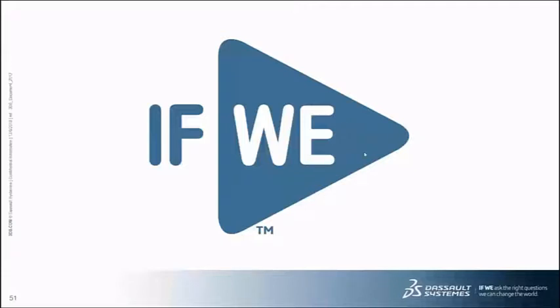How about dynamic implicit method to resolve convergence issues? Yes, I've started to use that more and more. And frankly, I prefer implicit dynamics with the application for quasi-static situations to static stabilized today. Static stabilized still has its uses, but I find myself more and more using the quasi-static implicit dynamics in lieu of static stabilized.